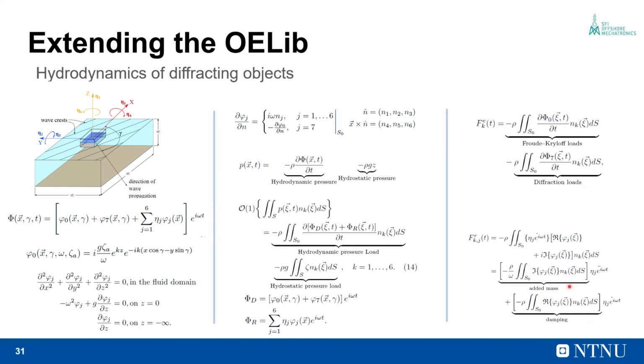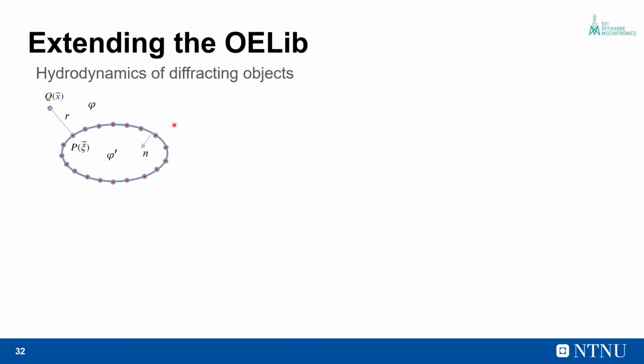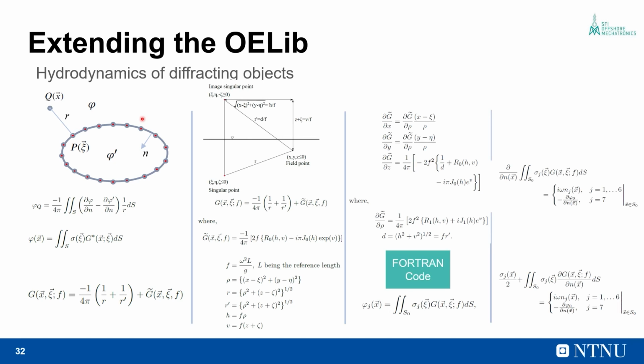And to solve this wave body interaction problem, we need to represent the presence of the body mathematically in a flow domain. And we do that by adopting the method used by Sir Horace Lamb, where he uses sources distributed on the body surface and the concept of the Green function to mathematically represent the presence of this body. And in this case, since we have waves, the Green function will have a steady part and an unsteady part.